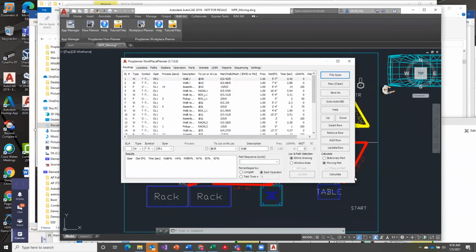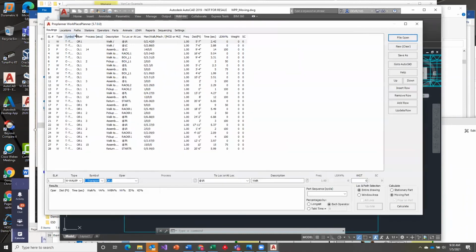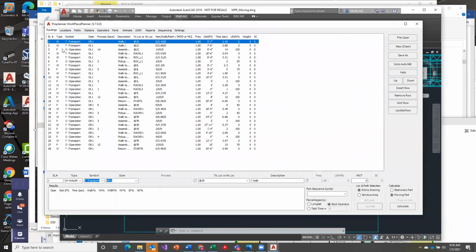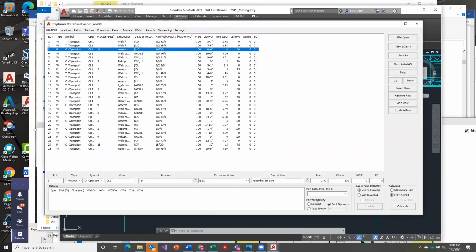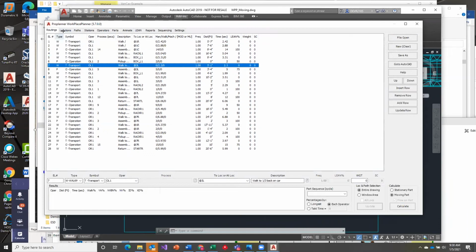And what we're going to see is something a little bit different now in our specification, our tasks. First of all, one thing you'll notice is that I do have my operators. In this case, I have a processing time. I use P, that's fine. And you have your W for your walk time. So M or P can be your manual processing time, machine dependent processing time or manual processing time. It doesn't matter. It's just a user preference. Depends on your reporting. Some people want to determine in their process sheet whether this was a machine dependent processing time or a worker dependent manual processing time.